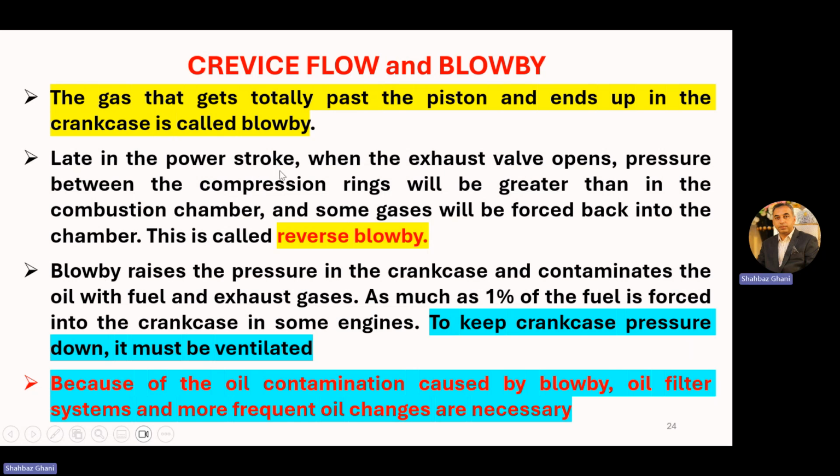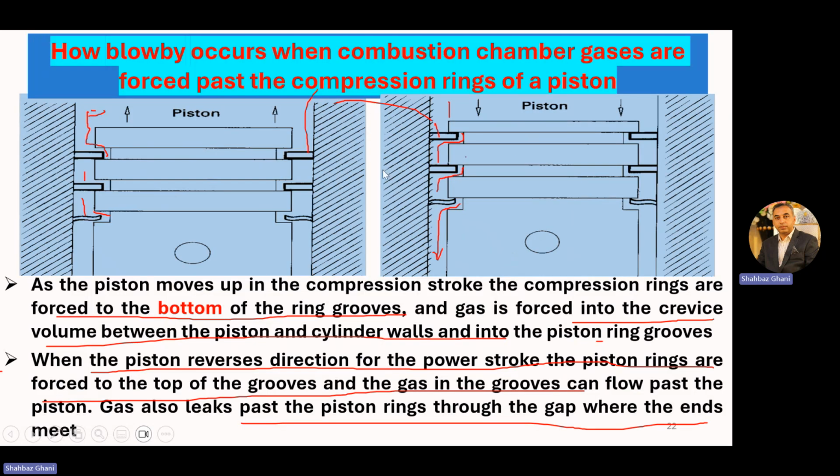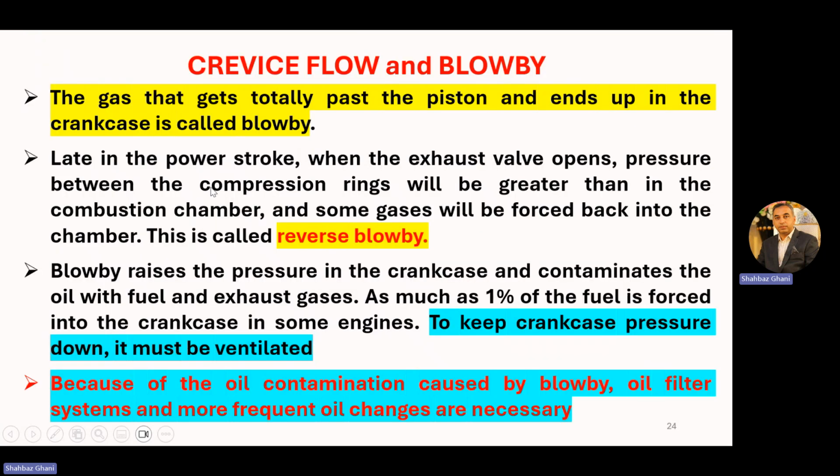Late in the power stroke, when your exhaust valves open, the pressure between the compression rings will be greater than in the combustion chamber. Your pressure here will be more than that in the combustion chamber.